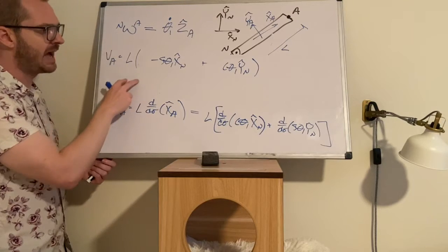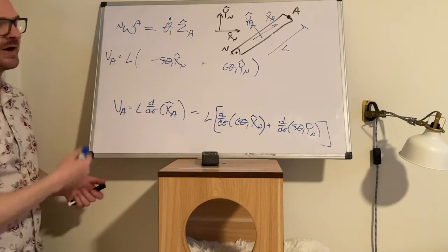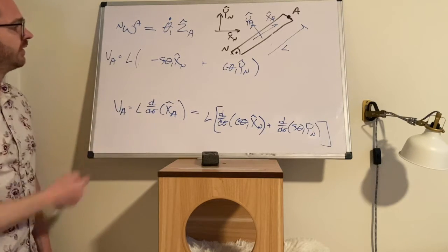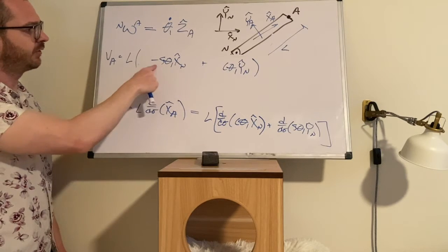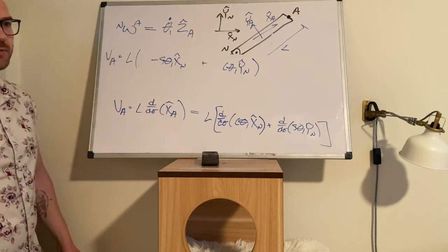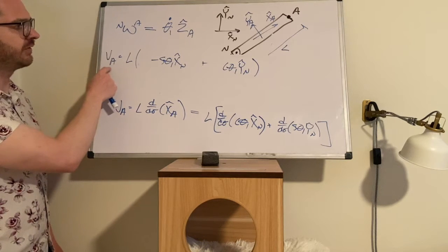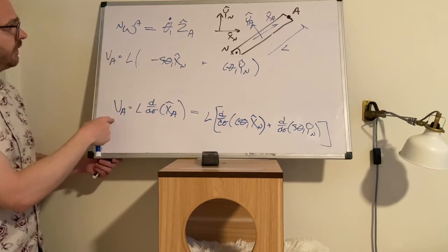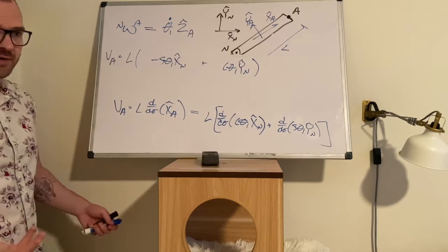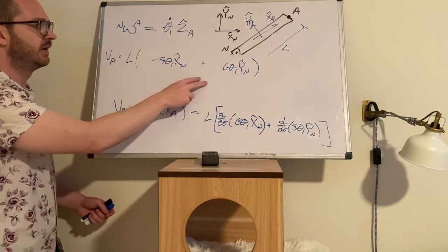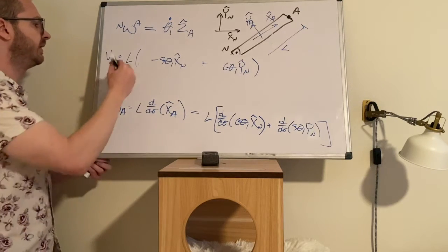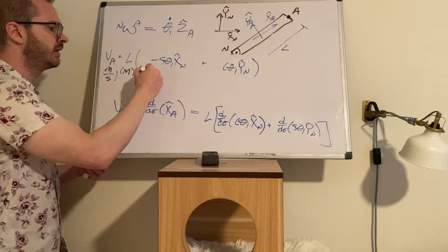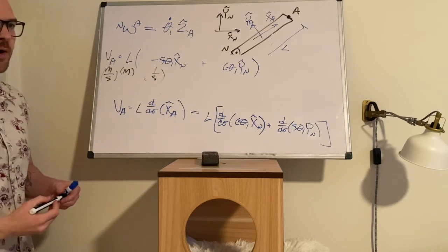If this were the correct answer, then we should be able to say that VA is equal to this. And there's some magnitude here, and it has direction, so it's a vector that checks out. What are the units? In the way that I've written it right now, what are the units here? This is a length, and then this is sine of an angle. Well, sine of an angle and cosine of an angle, those are ratios. There's no units there. So if this is all you write down, then you're telling me that velocity has the units of meters, which makes no sense. We look at position vector, it would have the units of meters. Hey, that's fine. So something else has happened here. And clearly if this is meters, and we know that the answer is meter per second, then somewhere in here we're missing a 1 over seconds, right?